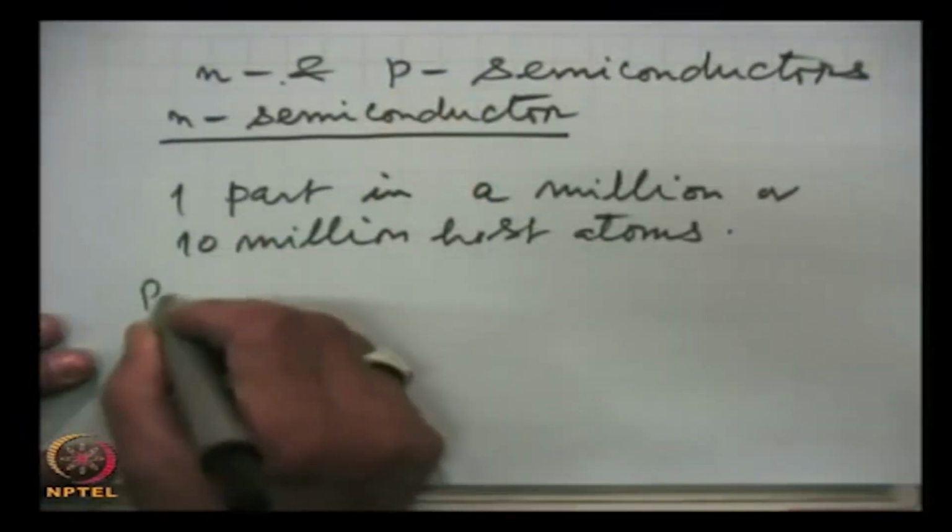One thing you should also remember is that in an intrinsic material, when we talk of holes or electrons, these electrons are the ones which are mobile when we apply a field. These are not bound electrons. They have come to the conduction band after breaking a bond and leaving behind an energy state, and that vacant energy state is responsible for the creation of the hole. Now, let me take one example of the N dopant, which is phosphorus.